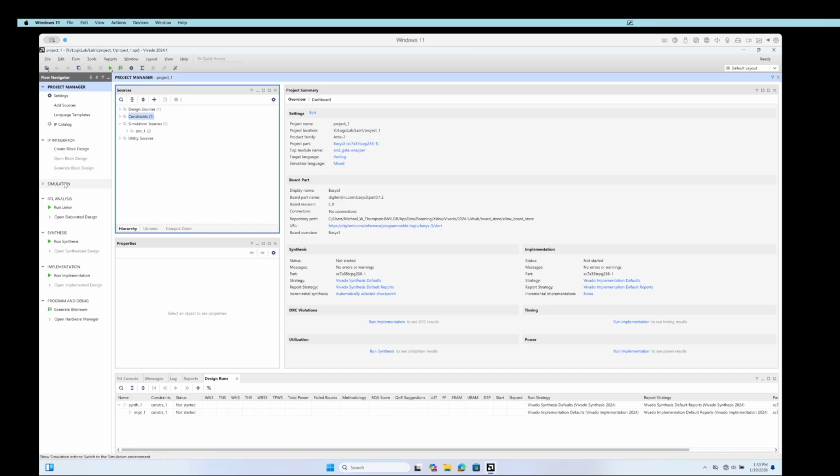So to get started with the simulation though, you want to make sure you're running the correct simulation file. Experience tells us that when you do this, you have to click here to see which file Vivado read as a simulation source. Now, I'm not sure why this happens, but often it gets the wrapper incorrectly inserted into the simulation sources.